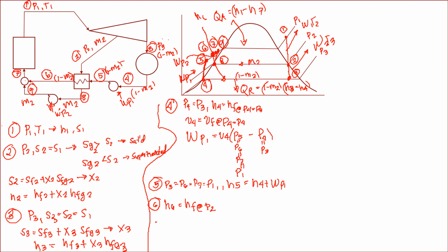Now again, point 7 is not known since we have to determine the mixture result. So we establish the initial mixture equation first, H6 and the energy equation and mass equation of M2. M2 multiplied by H9, of course we don't know the H9 yet, and the result is H7. So our main concern is H8 and H9. I will provide space later for this one.